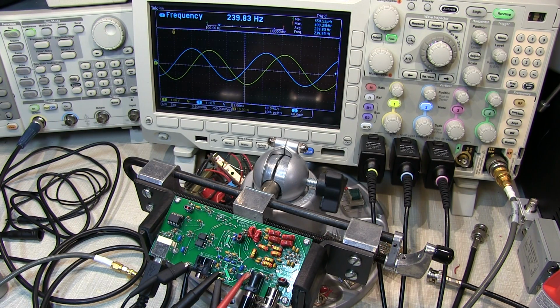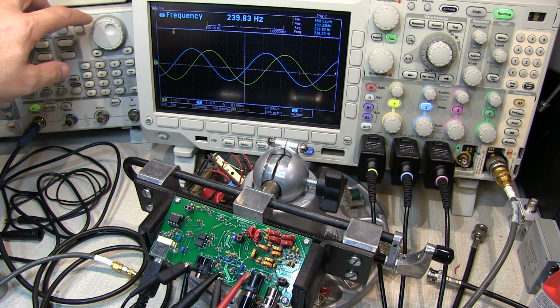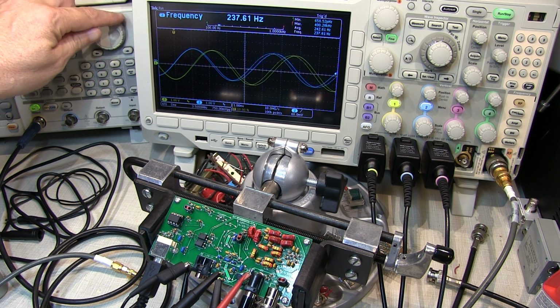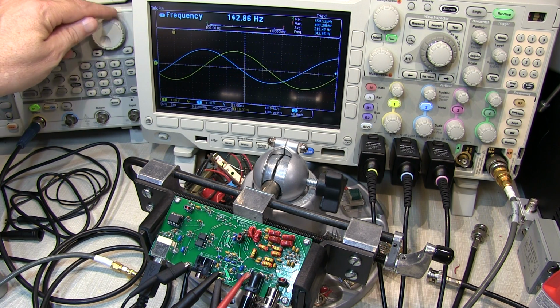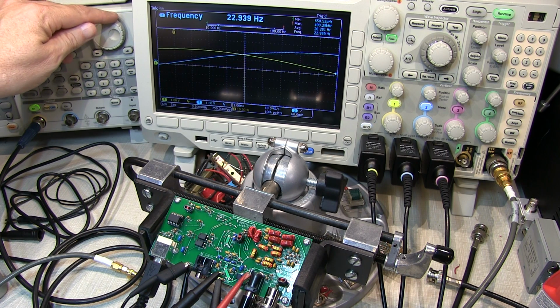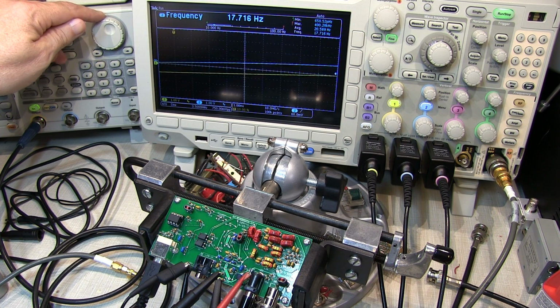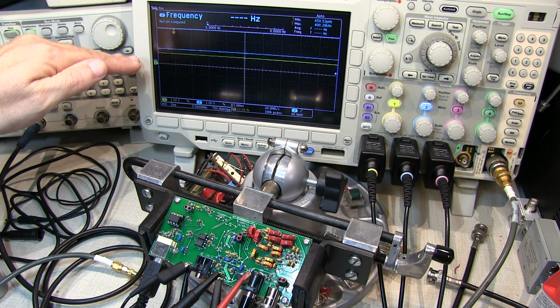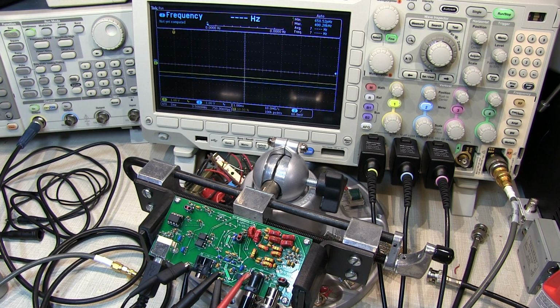Okay, a little last look at what happens in the receiver as we start changing the input coming in. If I adjust the frequency down, in this case, till I'm very, very close to being zero beated against my local oscillator, these 2 signals are going to be varying very, very slowly in time. I can get them moving real slow. It almost looks like just some DC levels that are moving up and down now. We've got the frequency dialed in really close, and that's exactly what you'd expect out of the Quadrature detector.